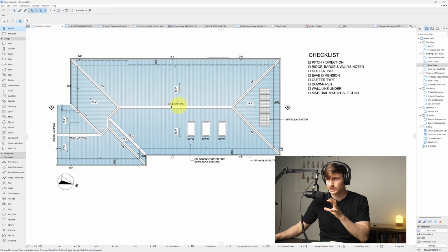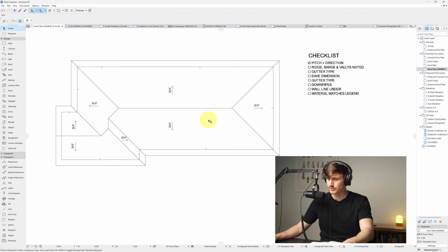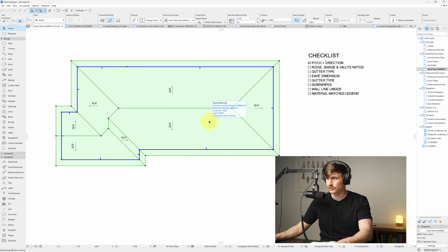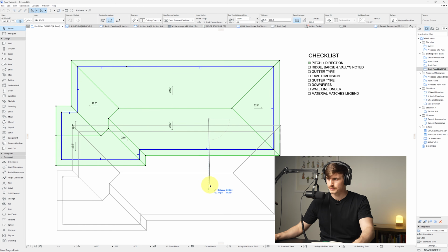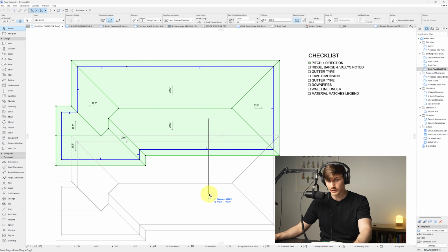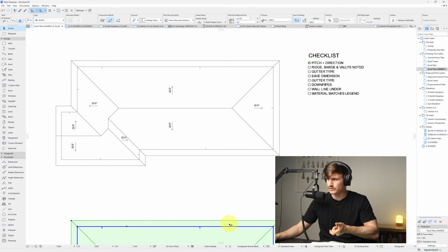So to create all the flashing that we see on top of the roof just here, what I typically do is I select the roof, I go Control D to drag it, and then I'll tap Control once to create a duplicate. From here, I'll type in a dimension, say 20,000, and hit enter. Just a dimension, I'll be able to easily bring it back up.